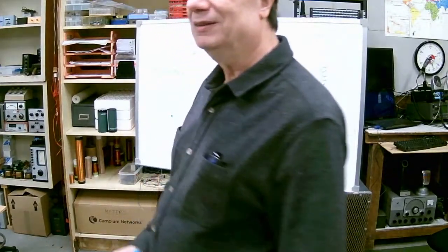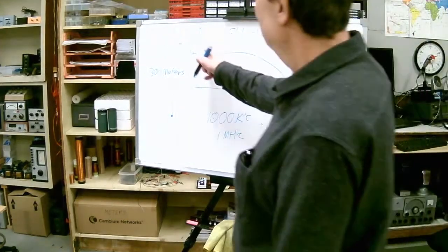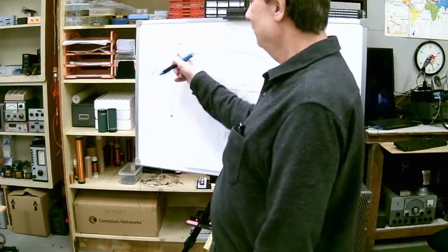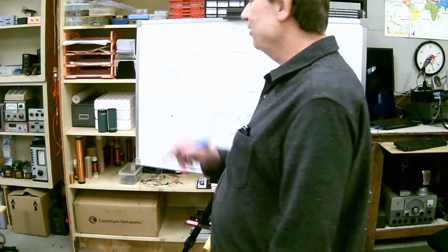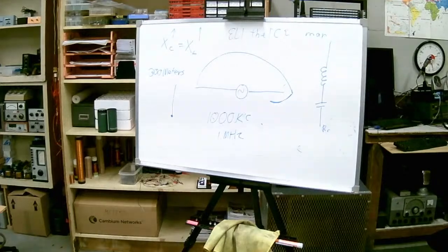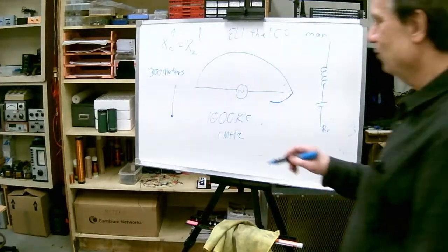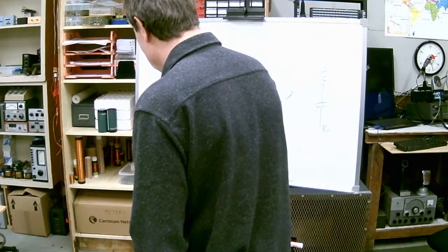You see the whip here. What's the impedance going to look like at the base of that? I would say high. Well, it's going to be very high, because capacitive reactance is very high. So what do we do to make that thing resonate? Like you said, add inductance. Right, we put a loading coil in, at the front end of your receiver.